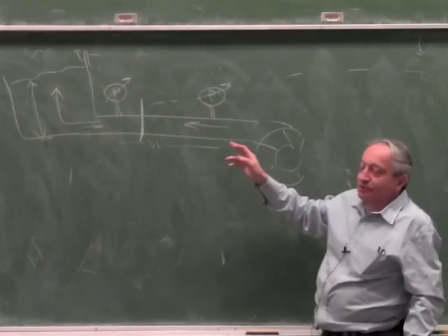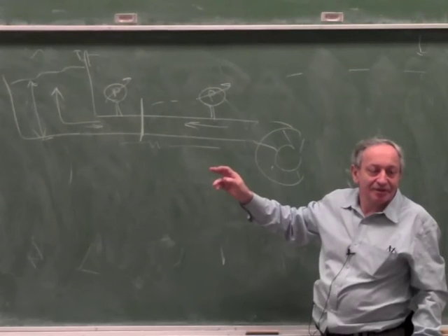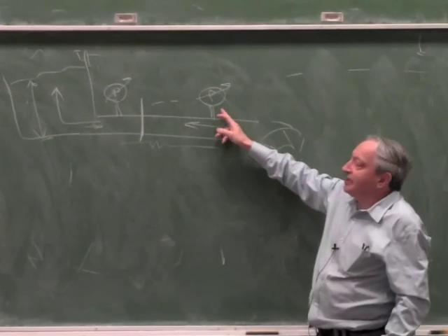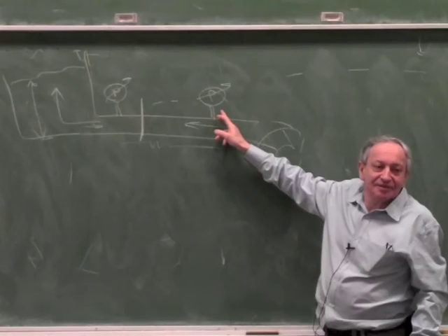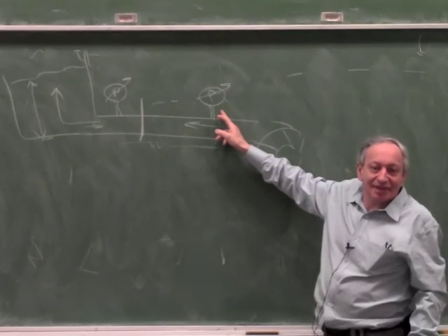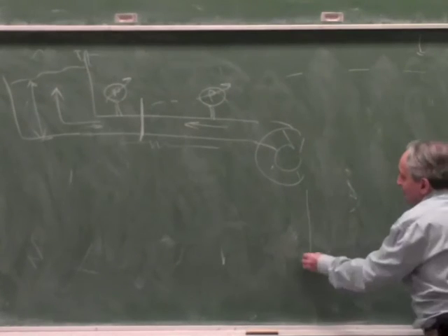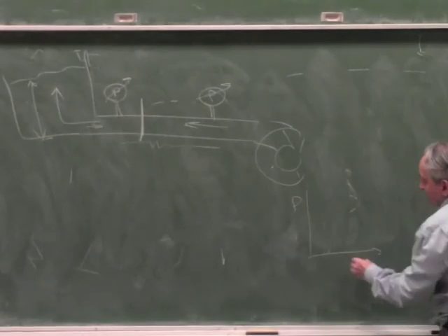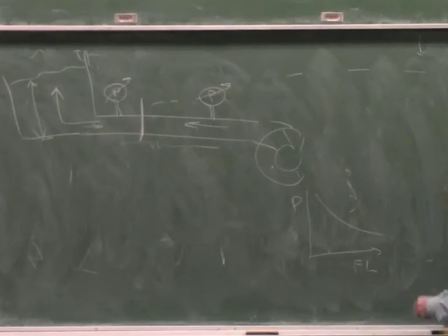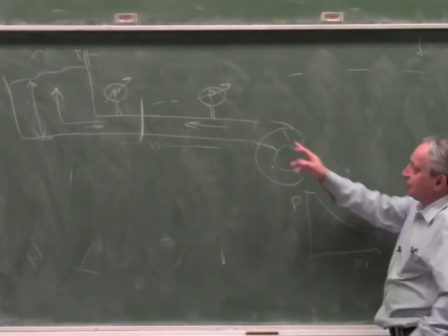So which will rise, which will drop? The one on the pump side will rise. Now, why would it rise? Because it has all this flow that's kind of compressing. Yes, because basically the pump has some graph, flow versus pressure, and most pumps, if this is pressure and this is flow, have a graph like this, so if the flow goes to zero, the pressure goes up.